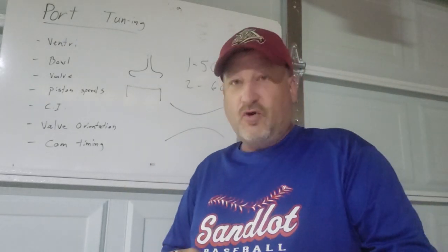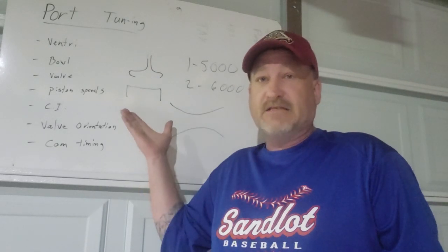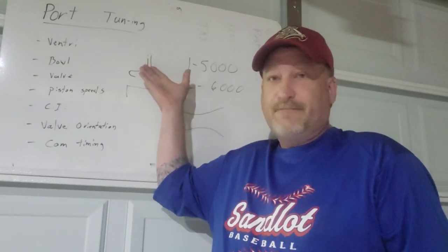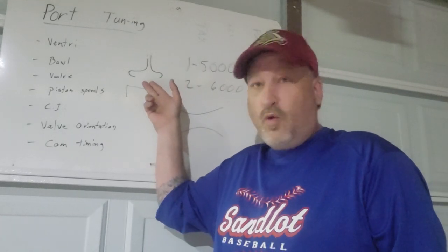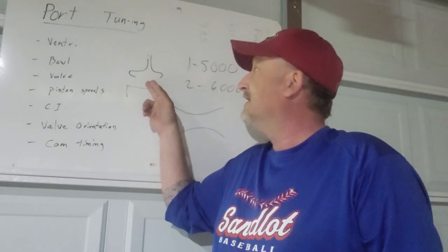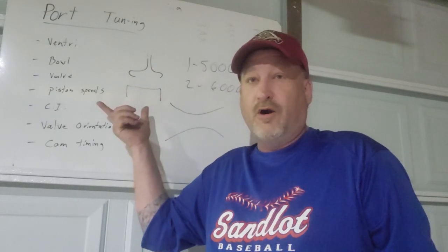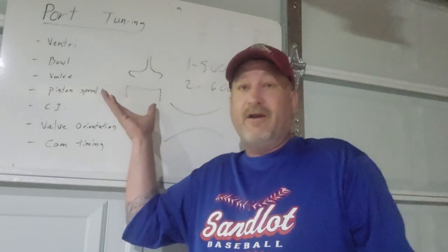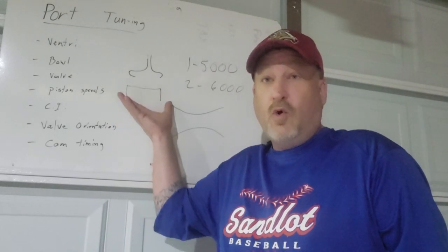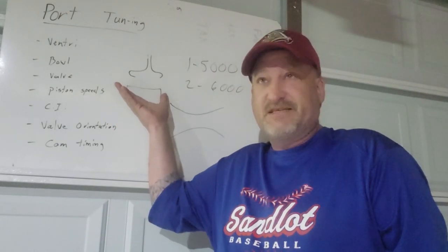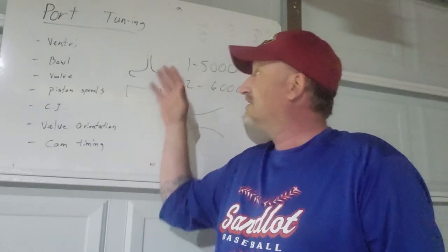Okay, as the valve is opening, once again, there's no vacuum necessarily pulling the air past the valve. It is the ram effect, the positive pressure on the backside of the valve, and the lower pressures, not necessarily negative pressures, but the pressure differences between the cylinder and that. And the bigger the bore, the more area is there to be filled. So the pressures will be a little bit lower on the cylinder side of the valve. Again, as the valve opens up, it is the ramming effect.